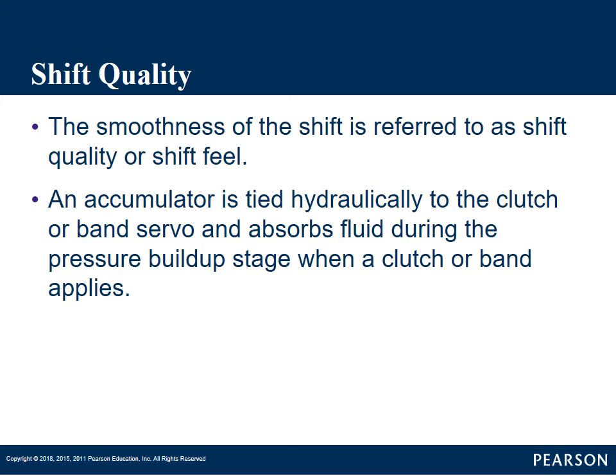We can shorten the shifts and make them really harsh to where maybe the clutch packs might last for a long time, but it really jars the vehicle. You're applying a lot of torque quickly, and customers are going to complain about that. About the only time you want real short and real harsh shifts is in race applications.